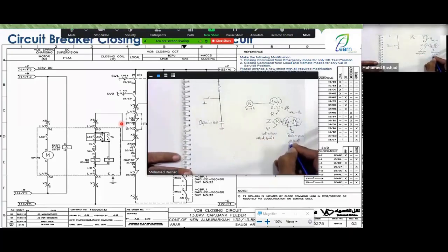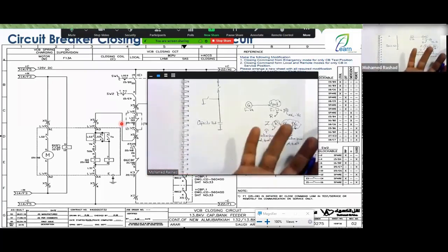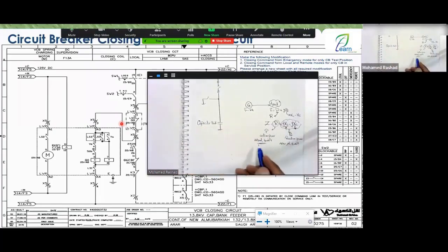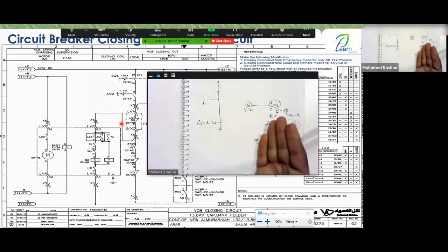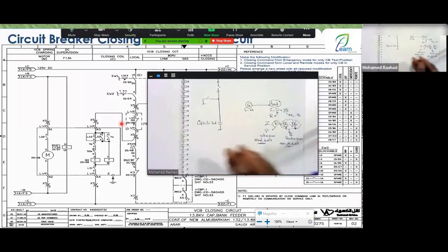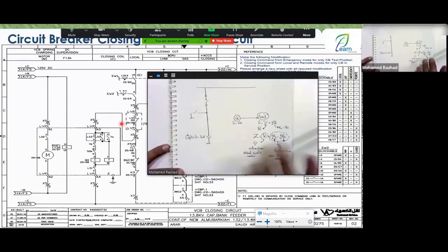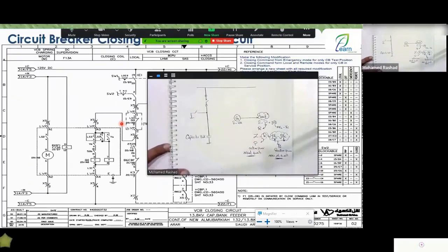What does that mean, engineer? If you have a load like a motor, the active power that the motor draws is the power responsible for moving the motor. It is the power that is converted from electrical form to mechanical form or kinetic energy. Reactive power is the power that is involuntarily drawn in the form of the magnetic field that transfers from the stator to the rotor to create mechanical movement. It is solely for the process of magnetization, or what we refer to as our field or magnetic field.